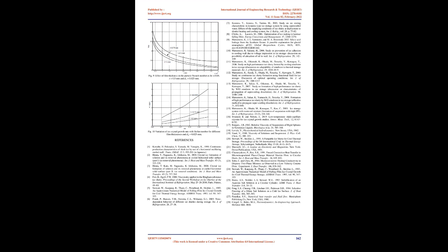The effect of the Stefan number on the distribution of particle Nusselt numbers within the film thickness at T equals 0.5 mm and DIN equals 0.025 mm is depicted in Fig 8. The increase in Stefan number increases the rate of growth of particle and consequently enhances particle Nusselt number. The effect of film thickness on the particle Nusselt number is shown in Fig 9. It can be seen that the increase in the film thickness decreases the particle Nusselt number. This can be attributed to the decrease in heat transfer and particle growth rates.